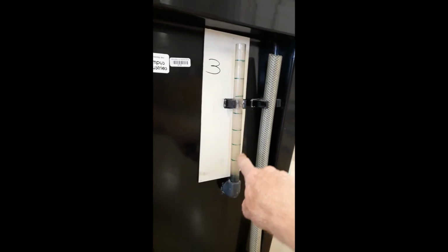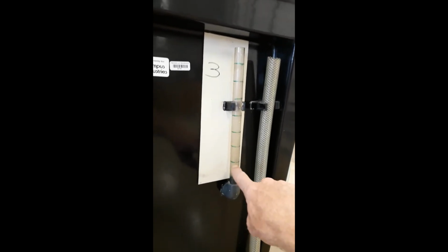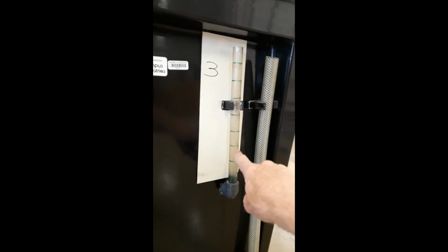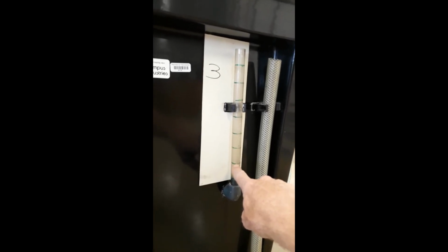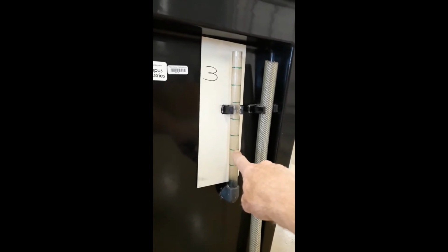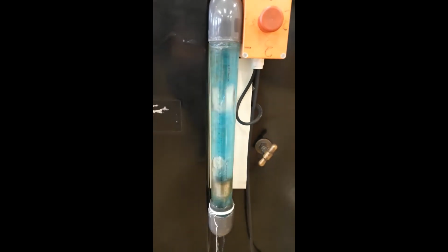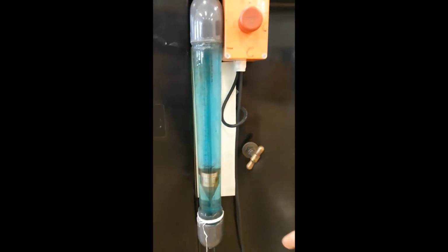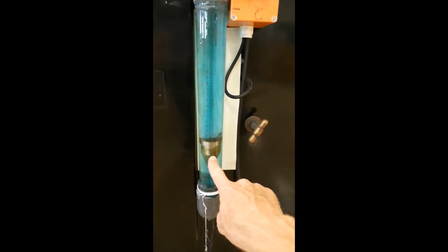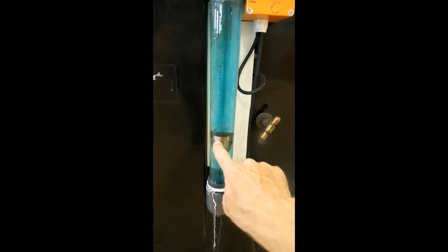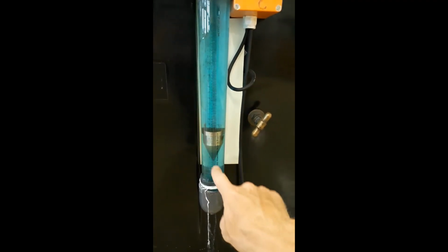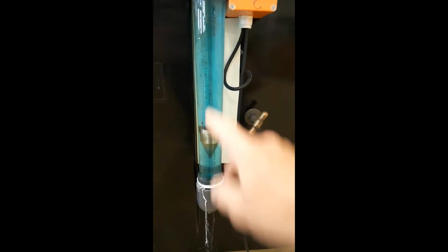Now on the sight glass for the small basin, there are markings on it, increments. All that means, these increments are marked 5 liters apart. So if the water fills from this line to that line, that is 5 liters of water. And here we have the Rotameter. There's the glass tube. There's some air coming through. And this is the float. And from the schematic you'll see this bottom edge of the float is where we take the reading. And the scale for this Rotameter is in millimeters.